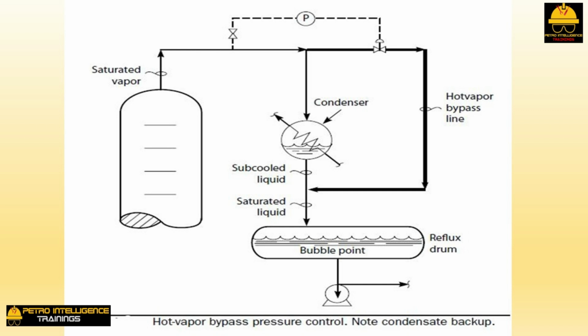Part of the surface area of the condenser is hence devoted to subcooling liquid, and part is devoted to condensing vapor. But how does this work? How does the condenser know, without any advice from us, how much of its heat exchanger surface area, which is supposed to be used to condense vapors, to divert to subcooling liquid? Let's assume that the liquid draining from the condenser is not quite cold enough to absorb the entire latent heat of condensation of the vapors flowing through the hot vapor bypass line. The vapors will then be only partially condensed.